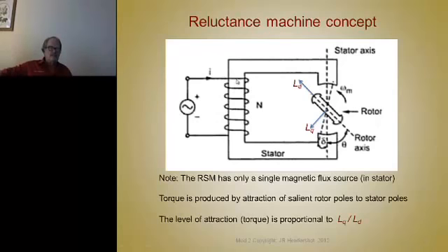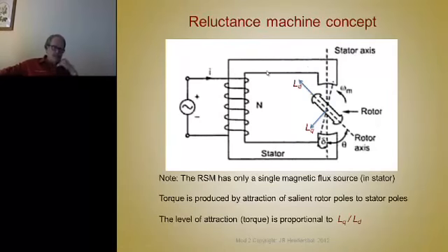So if we measure the inductance of this inductor, it's going to be quite high, because there's very little air in the circuit. All the flux is carried by this permeable core, very high permeability as opposed to air. So there's going to be a lot of resistance to the current buildup in this. The L over R is going to be a big number. So we call that inductance the D-axis inductance.